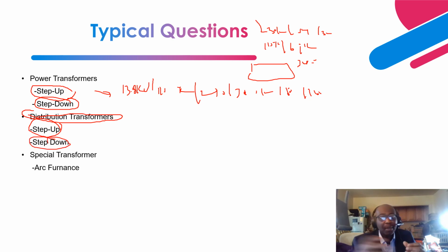For a step-up transformer, when it is used in the distribution, that is more of an upgrade or modification of the network, where the voltages are being stepped up to be used, let's say, for an industry that is being constructed in that distribution network, where let's say the distribution voltage level is 13.8 kV, and you're stepping it up to, let's say, 69 kV or 34.5 kV.